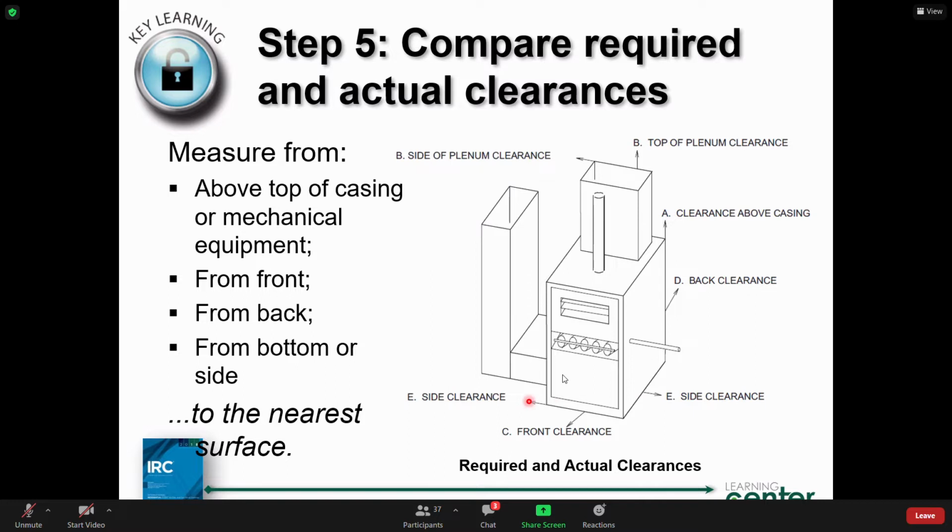I know we use it for fire resistance ratings and things of that nature, but drywall, wood construction, things of that nature, there's a test. You may want to write this down. It's called ASTM E136, American Society for Testing of Materials E136. And if you've got a Google by you, Google it. You'll see exactly what this test is. It will burn materials and look at their flammability and their reduction in volume. That's the true test for combustible materials.